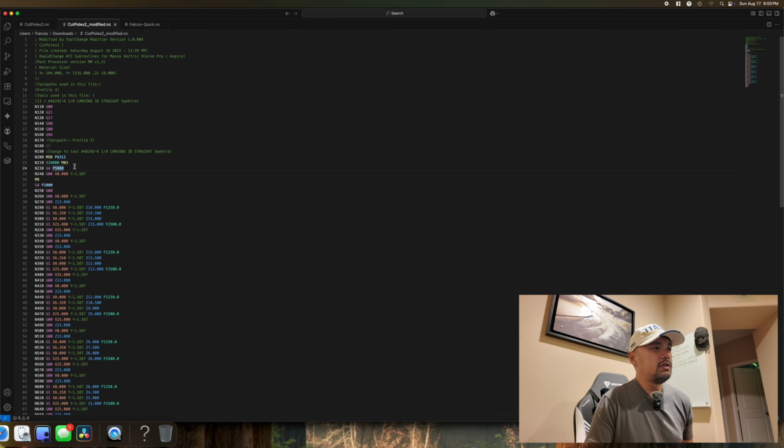So here there's again an M98 P200, the spindle RPM, and then there's already a delay that's part of the customer's original file. And then look here, the X and Y is executed, then the M8, then the delay, and then before it resumes the actual job, like a Z plunge here. So this is the ideal.